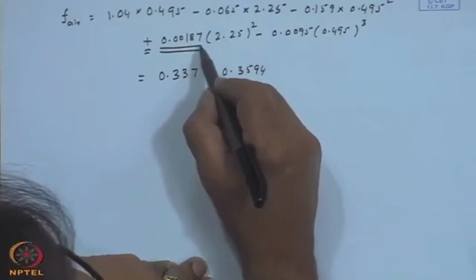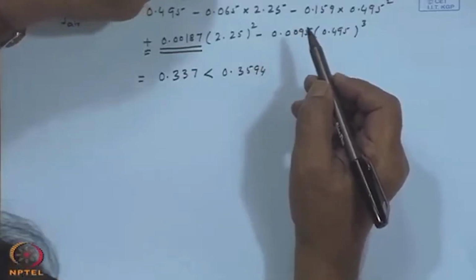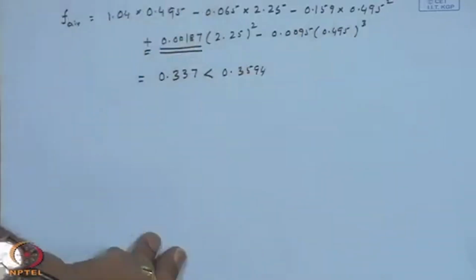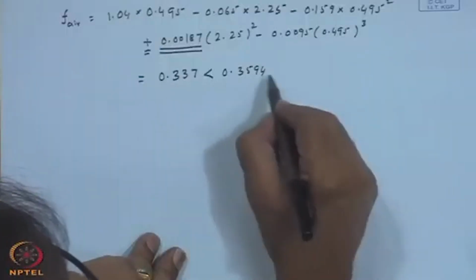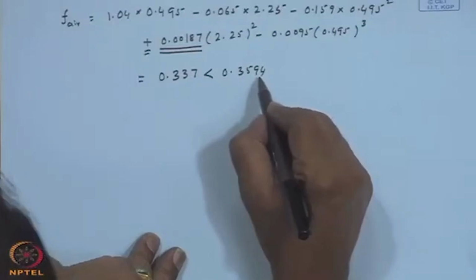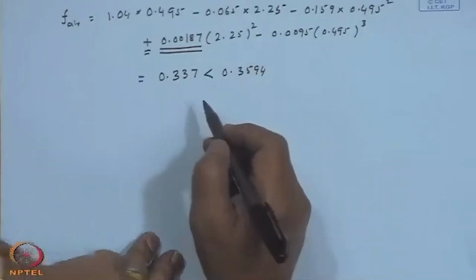One reason could be, people attribute that at a higher flow rate the storage is very much disturbed. So, stratification is not maintained, and consequently the effective temperature goes down, making the effective solar load fraction lower than what it would be at the standard flow rate. So, the standard flow rate is sort of an optimum flow rate also, right.